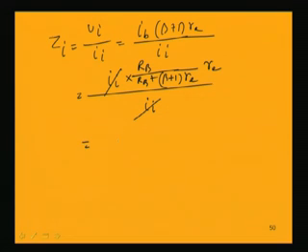So, now this is equal to RB into beta plus 1 RE by RB plus beta plus 1 RE, sorry, this is beta plus 1 RE, because I am writing IB with this quantity and beta plus 1 RE is there.